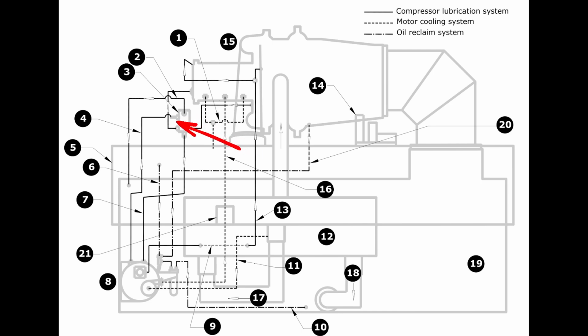Those are processing through this same port, separates the oil out, lets it fall back to the tank, and then that same vent takes whatever refrigerant got involved in the oil lubrication process and makes sure that it can vent out properly.